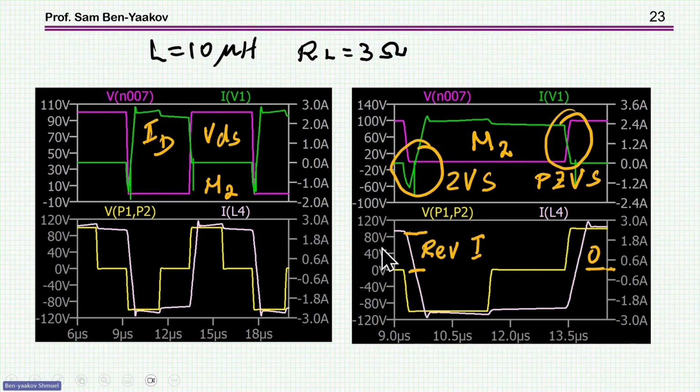So we have a section here that is maintaining, remembering the previous polarity, which is doing the trick of this reverse current. And then we move on. So here we have a very nice soft switching, zero voltage switching, of course. Here we have a pseudo zero voltage switching, which is the other case. Again, it has to do with the question of how fast can we change the current, as I've said.